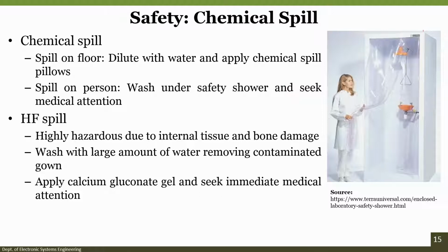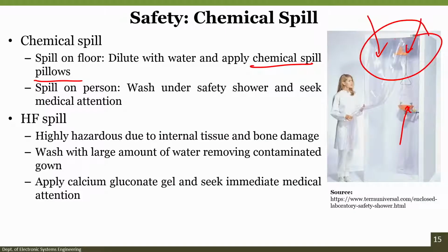Then you can see here there is a curtain, and this is a shower, and this is for the eye splash. In case there is a chemical spill on the floor, dilute with water and apply chemical spill pillows. You need to use chemical spill pillows, and before that you need to get trained on how to remove the spill on the floor. For a spill on a person, if there is a chemical spill on your colleague working in the clean room, wash completely under the safety shower and immediately seek medical attention.